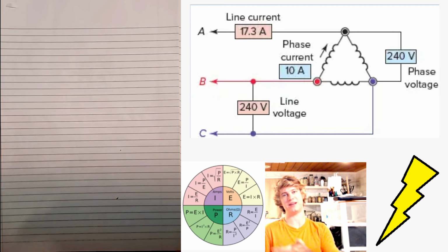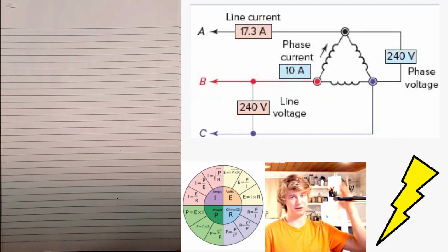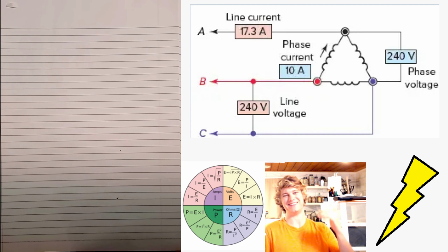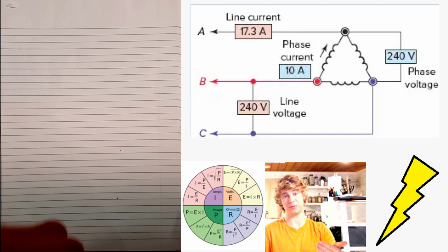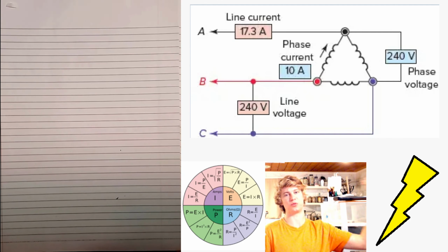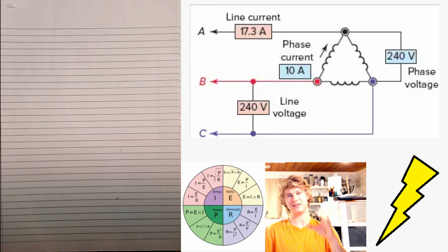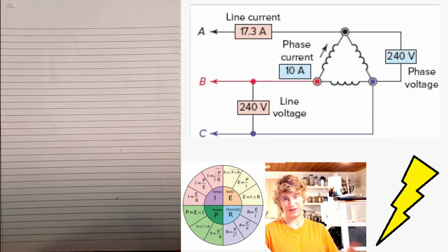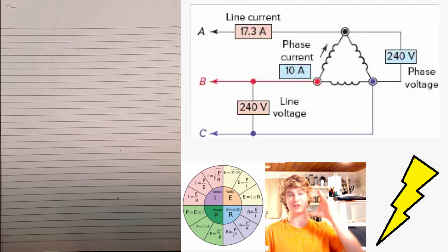Now we need to comprehend that the current goes through the rotor or phase, and it's measured at the end of where that rotor terminal is. Because it's going through that phase, you're measuring the current, you can see that these are combined and they're not just added together. You don't just get a simple 20, but we see a 17.3. This is because the line current and the phase current are different, to where, again, your phase current is going to be a smaller number and your line current is going to be a bigger number, since they're going to be combined.